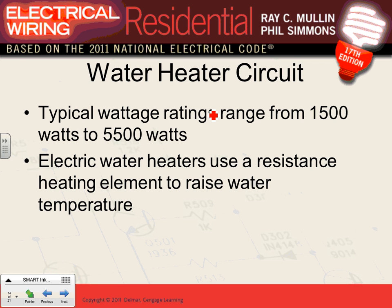What I owe you later on is a calculation example to refresh your mind about the disconnect, the overcurrent protection device, and so forth. Can I get you guys to understand a pump is a motor? A motor needs an overcurrent protection device, a circuit breaker, a branch circuit conductor, a disconnect for safety, an overload, and a controller so it can control the system. Any comments about submersible pumps, which are motors? Can I have a thumbs up, Chad? We know it. Please read this one, guys. Again, we're designers. The more you know about the different electrical equipment, the better you will be.